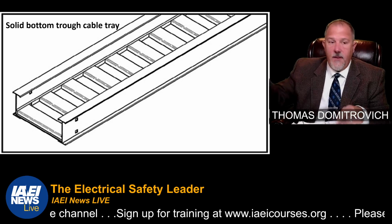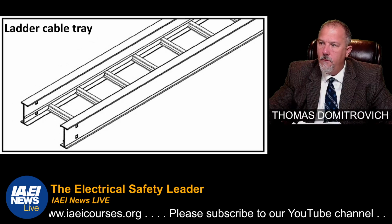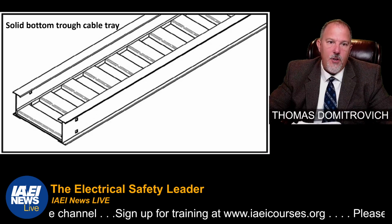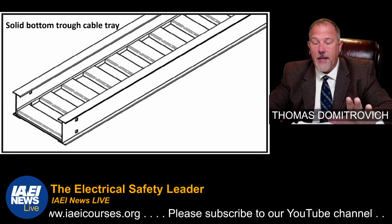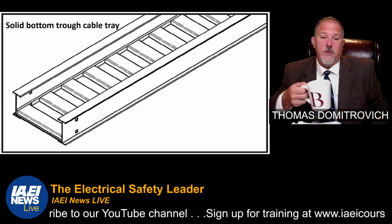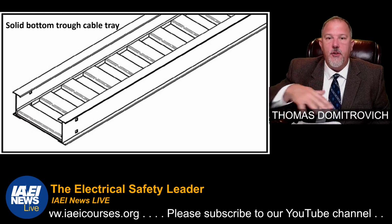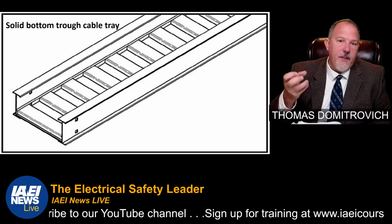Obviously, in the previous ladder cable tray, without the solid bottom, moisture and everything can go through. With a solid bottom tray, you've got to consider the fact that you could have water settling in there, depending upon the location. So think about where you're going to have this, and you might need some weep holes drilled. Follow manufacturer's recommendations. In many cases, they'll have you drill a weep hole about every 3 feet to limit that water accumulation. Water is not good. Your cables might be rated for moisture, but you've got to think about the integrity of the cable tray itself.